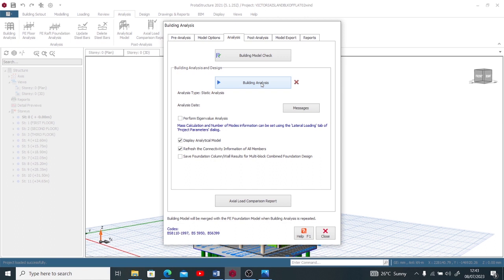Do not forget, as long as your building is exceeding 10 meters, that is to say, going beyond a 3-story building using an average height of 3.1 meters, then you should consider the wind effect and the wind load appropriately.